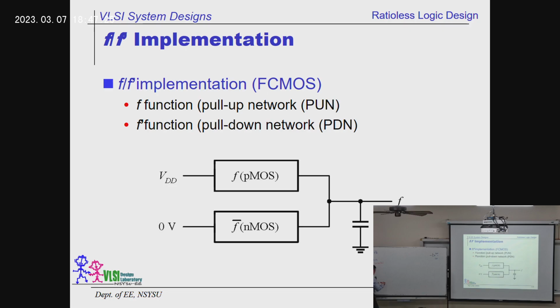So we understand that in the bottom of our design, to realize this gate, we are going to have two N transistors. They are floor-planned as a pair in parallel. This is the A input and this is the B input. This is for the bottom. Based on that observation, we are going to have the output over here, and of course, we have a load. This is the basic idea.